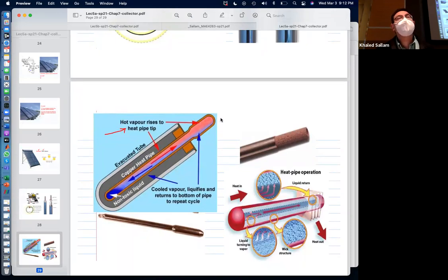What's a heat pump? A heat pump is a compressor, evaporator, condenser, and a throttling device that circulate the heat from the low to the high. So how does this guy do it? How does he take the heat from here to here? There is a liquid working fluid, propane, some kind of exotic fluid. It's not water. That fluid inside will boil and become vapor at this temperature. So this temperature here is hot enough to make it become vapor.